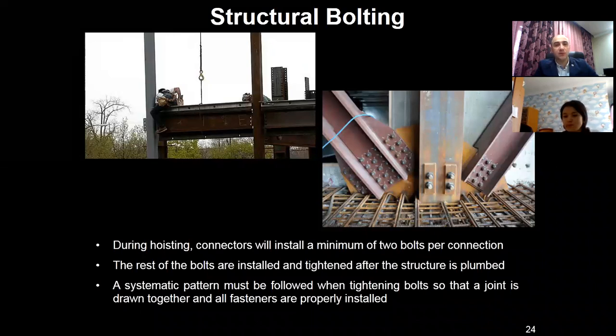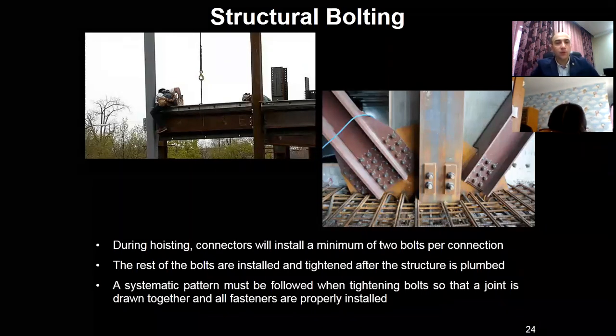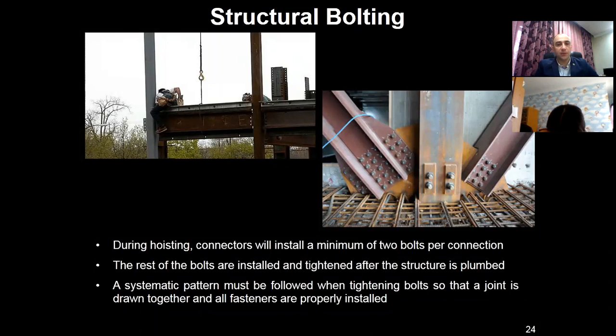By using geodetic equipment, the height of the beam will be checked, and only after checking all the needed parameters will the hoisting method be released and all bolts tightened. It will be fastened according to the requirements from the drawings and recommendations.